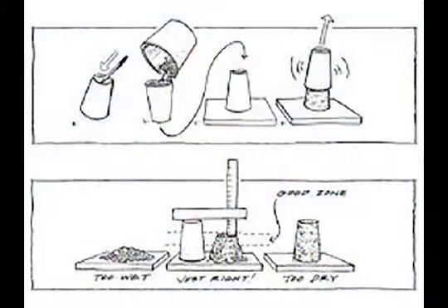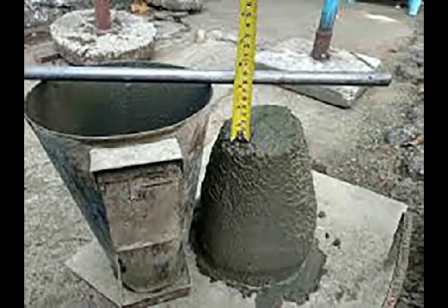The slump test, like I've said, is used to ascertain the workability of concrete. Workability of concrete means that the concrete can be handled, transported and placed without segregation. The slump test is also used to ensure we use the appropriate water cement ratio in concrete work.